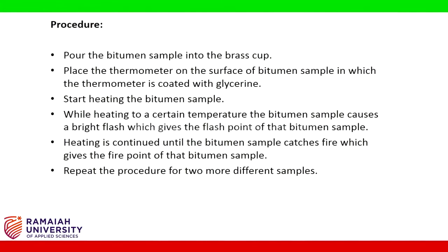Procedure: pour the bitumen sample into the brass cup. Place the thermometer on the surface of bitumen sample, in which the thermometer is coated with glycerin. Start heating the bitumen sample.